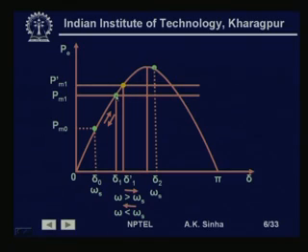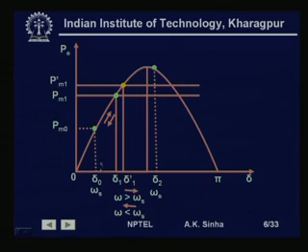So, from a super synchronous speed, that is a speed higher than the synchronous speed, as we move on this, the speed will start reducing, though P will also keep on increasing, and because of this there is going to be deceleration, or decelerating power will be available, which will try to reduce the speed of the system, and so we are going to have lesser and lesser speed coming into the picture, but all this time the speed will still be super synchronous.